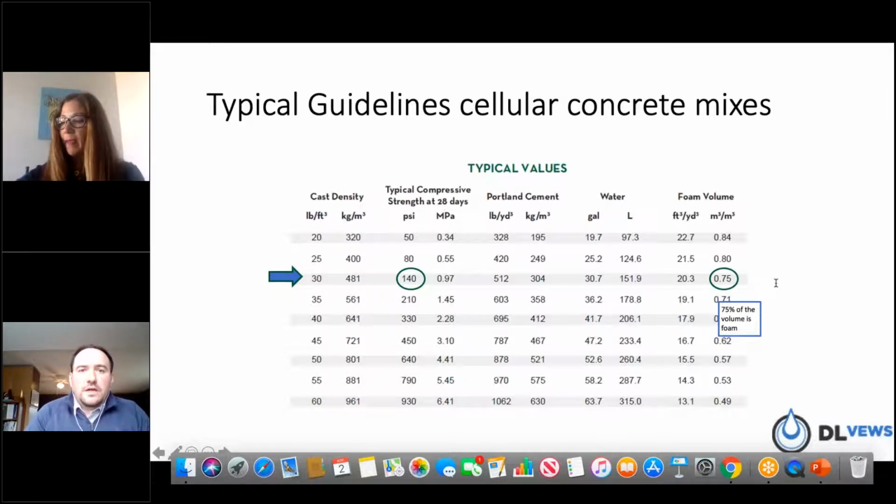All too often I see a lot of compressive strengths, whether they be in DOT specifications or just a private job specification. And the compressive strengths, you'll notice countrywide, will vary depending on the owner and the final design needs. I absolutely encourage everyone, whether it's a DOT or whoever the owner or engineer may be, to go ahead and specify a compressive strength, bearing in mind, and this is good we bring this up on this chart, Cassie, so thank you, that the compressive strengths on this chart are significantly greater than, again, a well-compacted soil.